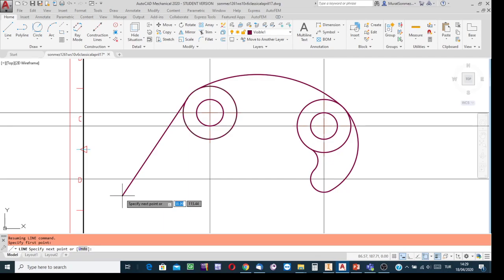And also, thanks to keeping the dynamic input button along the status bar on, yes, on position, we will have a dotted horizontal line, okay, it is the reference for inclination angles, and a dotted circle arc, okay, extended from the dotted horizontal line to the line which is about to be created.